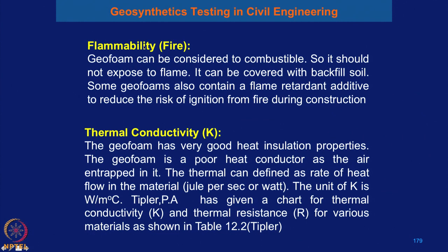Now, flammability means fire. So geofoam can be considered combustible, and it should not be exposed to flame. As I told you, it should not be exposed to any flame, and it should always be covered with backfill soil. Some geofoam also contains a flame retardant additive to reduce the risk of ignition during construction.